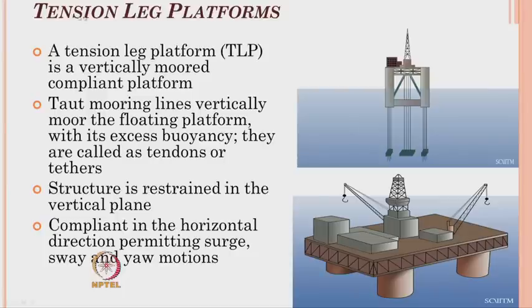Now, why is this called a tension leg? Or let us ask the question, how is tension always in place in these legs? When the platform is made to free float, the platform is brought to the site, the cables are free to float, and the cables are anchored to the seabed using the connections as shown here. Once the platform is deballasted, the platform, because of excessive buoyancy, will try to move upwards. The design is such that the buoyancy is much larger than the weight.